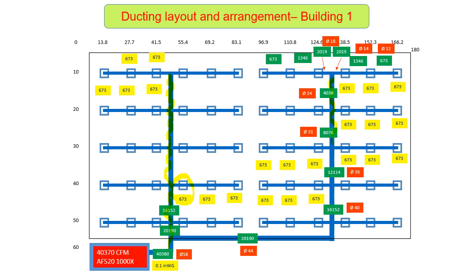And also here we have two main ducts, and per duct we will have about 20,200 for the main duct, because we have at the beginning in the AHU about 40,400 approximately, and we divide into two, then per main duct we will have 20,200, and from here we will reduce further, and it is to remember that a diffuser will have 673 CFM.